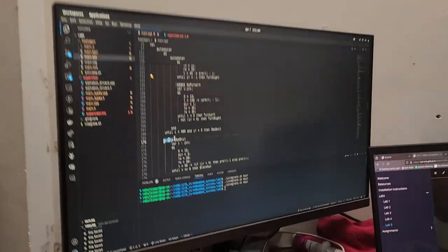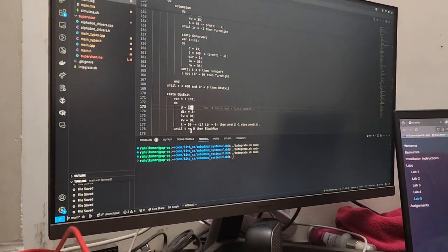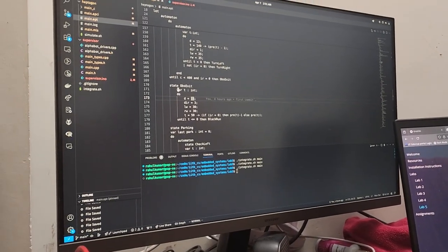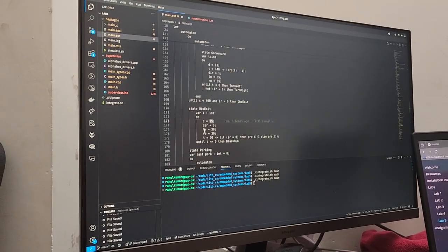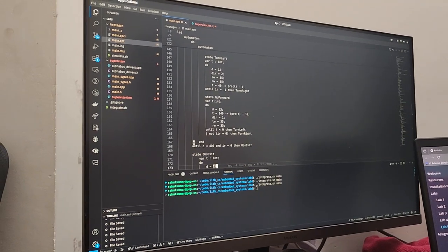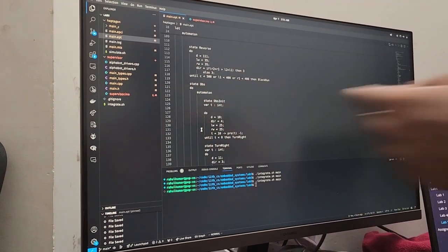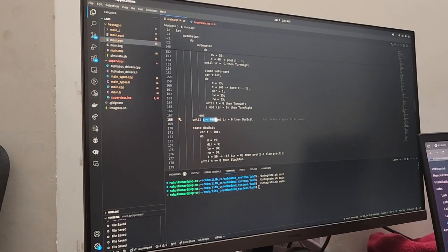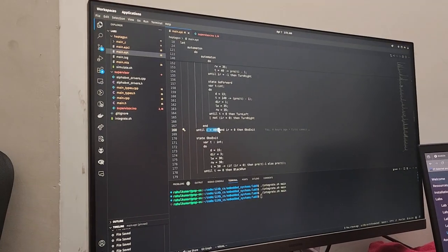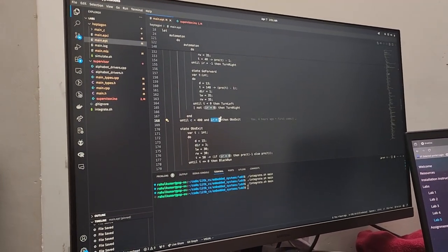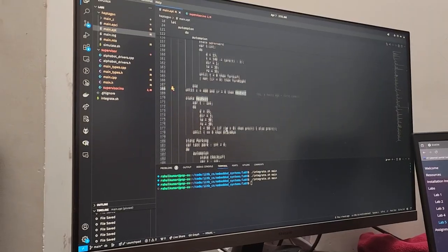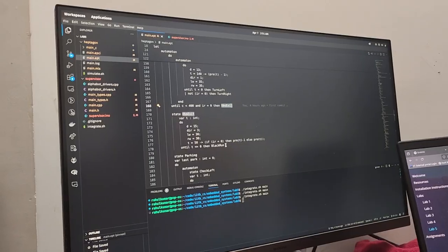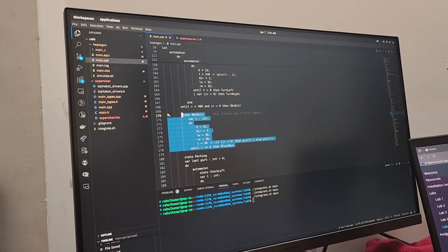Now basically here comes the exit part. So it goes outside of this OBS state, which is the obstacle navigation state. Once it recognizes a black line, that is a low value, and there is no obstacle in proximity, it will exit. Now coming to this state, it is nothing, it just turns towards the right till it centers itself, and then it will continue the black run, that is, going on the black run.